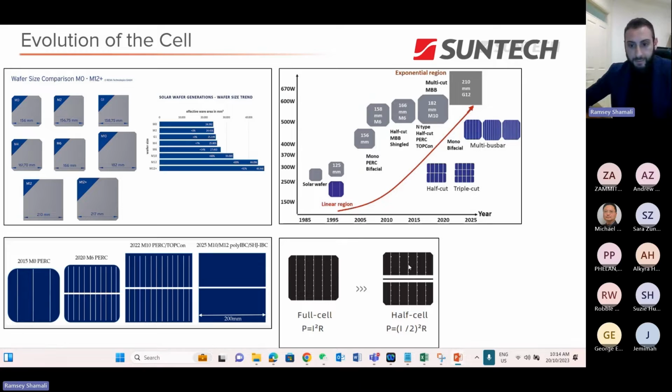The half cell is the more mainstream current configuration because of its enhanced benefits, such as lower operating current to be more compatible with MLPE and inverter power conversion equipment, as well as reducing power losses for any disturbance to the cell, to minimize loss on the whole module. As you know, the power and current relationship is proportional to the square. So if you halve the current, it will be 4 times less affected.